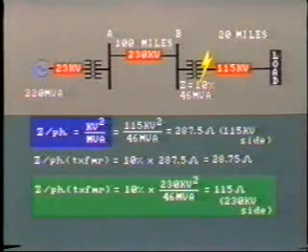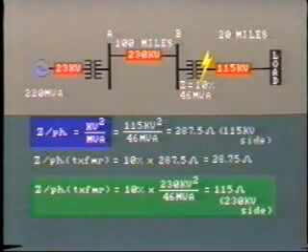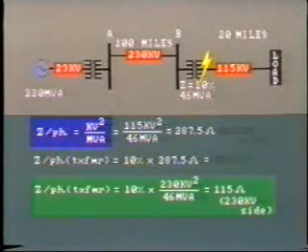This is an important conclusion. The ohmic impedance of the transformer is much lower when measured or seen from the low voltage side. This means that in order to add the different impedances in the system or perform calculations, we'll have to do a lot of number crunching as we go from one voltage level to another.